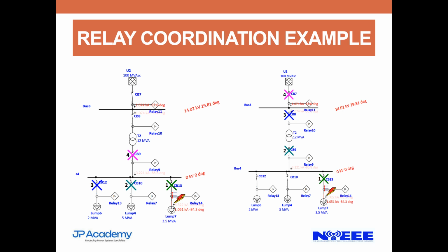Just as most of you have said, this on the left is actually wrong. This on the right is correct. We need to understand that fault isolation is different from relay coordination. I intentionally put this here as a relay coordination example.